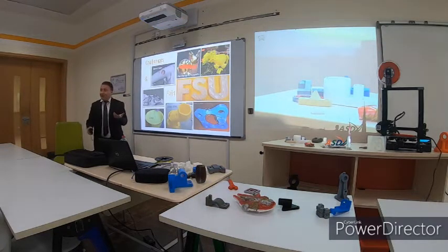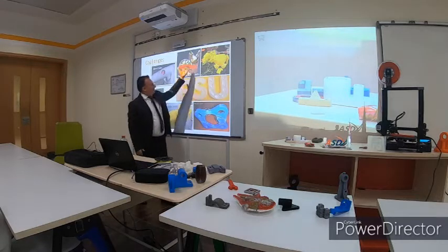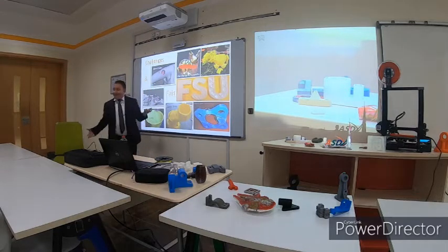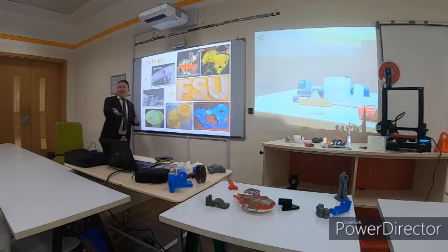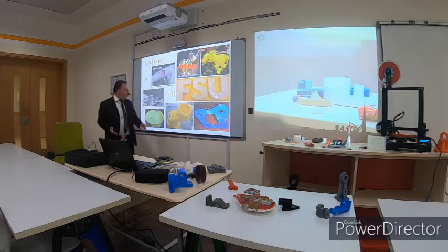Also there are challenges and fails. See, all these are fails. People don't show you the other side. You have layer shift, sometimes without any reason, just a mistake in calculation or in parameters. You have stringing, which is really a disaster.